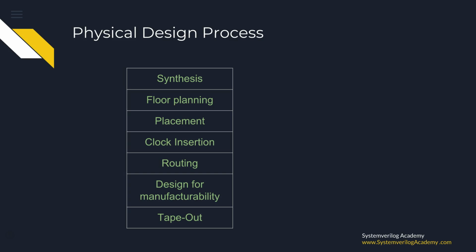Nowadays, the final photomask will be delivered in GDS2 format. It is a binary file format representing planar geometric shapes, text labels, and other information about the layout in a hierarchical form. The data can be used to reconstruct all or part of the artwork, to be used in sharing layouts or creating photomasks at the foundry. All the steps in physical design are explained in a very simplified manner here, but remember, in actual exercises, all of them are too complex, costly, and time-consuming.